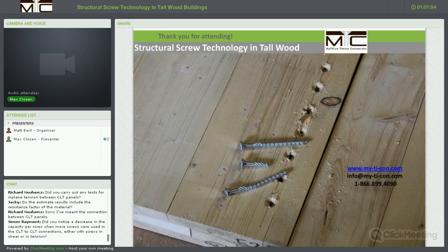For our design values listed here, we did apply a group action factor. Basically, we went into the CSA O86 again, applied the JG factor, which is the group reduction factor for the CLT connection systems as per design code. In some areas, it might be a little bit over conservative as the JG gets very small, 0.8 or 0.7 in some areas. So you have a 30% reduction of capacity there when you largely increase the amount of fasteners in your connection.